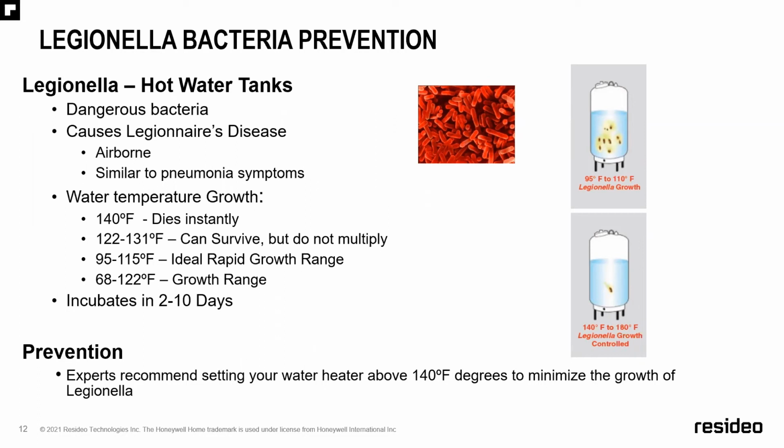So again, 140 degrees, you want to make sure we're killing that Legionella, keep the family safe, keep the tenant safe, or anybody that's attached to this tank style water heater. And again, there's experts out there recommending your water heater be set at 140 degrees to kill Legionella.